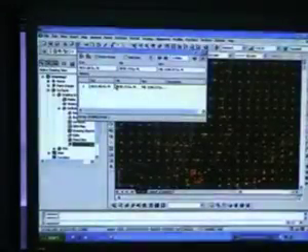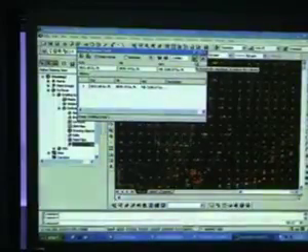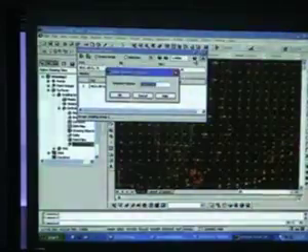Okay, so let's say it's like OGL. And then comparison surface, I'm going to select grading group 1. You just click anywhere outside, it does the calculation for you. Loading volume tool, so that it will appear here. Now, this button here automatically raises or lowers to balance volumes. Just select it. So this is where we put in what the final volume we want to be, so that it will do the balancing for us.